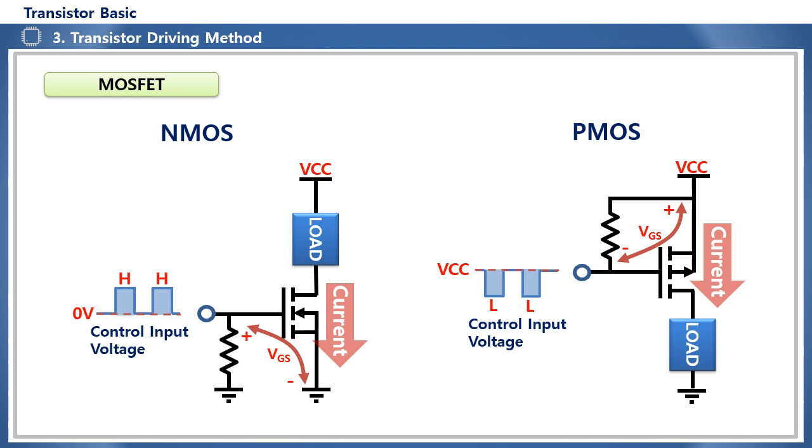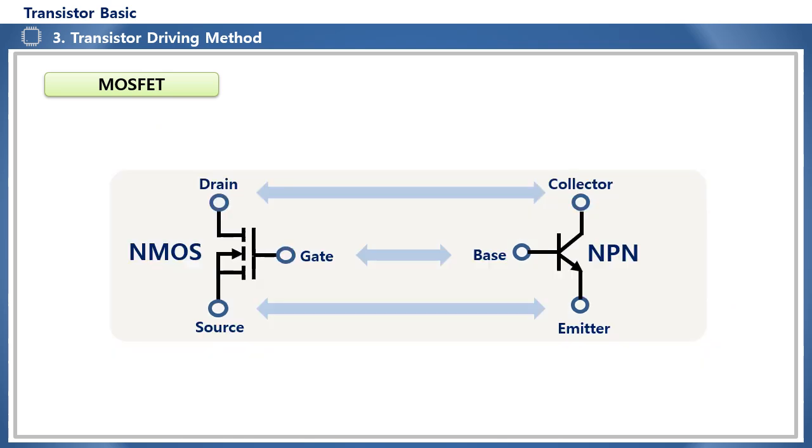The direction of the control voltage and turn-on current of these two types is somewhat difficult to intuitively understand with just the component symbols. So first determine whether it is N-channel or P-channel, and then recognize that NMOS has equivalent channel current characteristics to NPN and P-type MOSFET has equivalent channel current characteristics to PNP. Then, simply remember that the control method is voltage. That is, since the MOSFET and bipolar transistor are matched in terms of drain and collector, source and emitter, and gate and base.